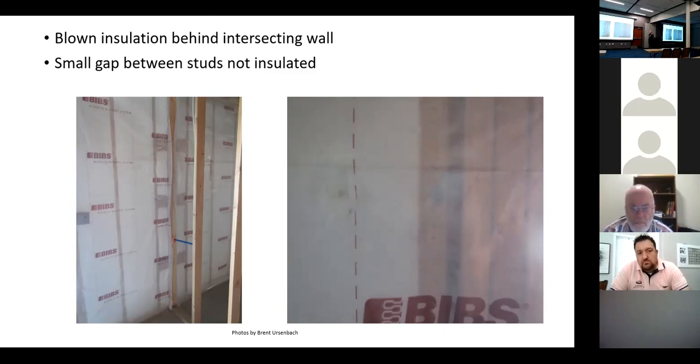So every pressure imbalance we create in our room, and it happens all the time, we're shoving the moisture into our walls. And at times of the year, when the conditions are right, we hit dew point and we condense on the backside of the wall. And I think, in my opinion, that the vapor barrier that we tried to put on that isn't tight does nothing but inhibit drying. You know what I'm saying?